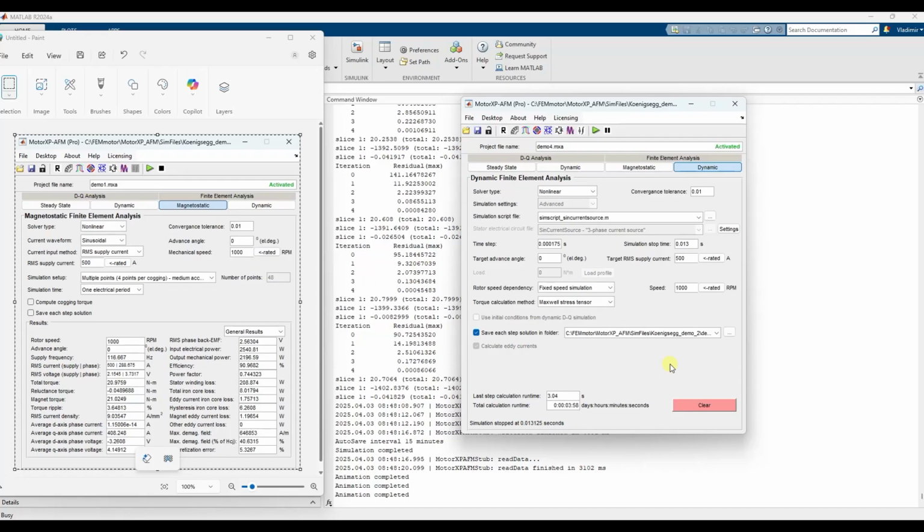What I usually do is apply a correction factor, where I just decrease the number of laminations. I look at the Steinmetz model results for losses, let's say for sinusoidal excitation, and then I correct my lamination model for transient eddy currents, decreasing the number of laminations until I match the transient eddy currents with Steinmetz, and then I can apply PWM just to see the effect of PWM on eddy currents with the transient model. I see. I understand. And then you can use that as a correction factor for the Steinmetz later on for magnetostatic.